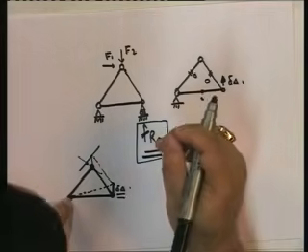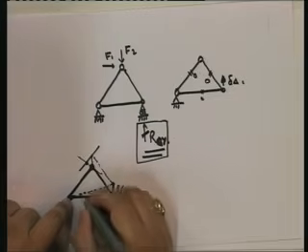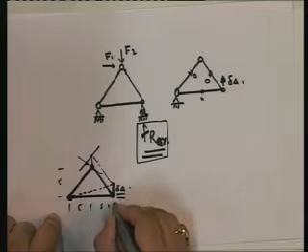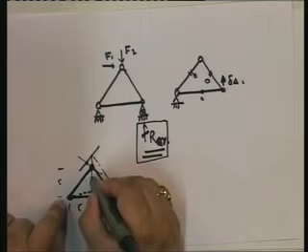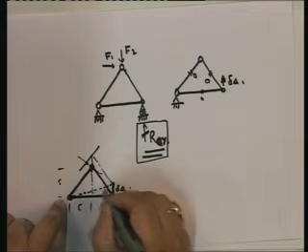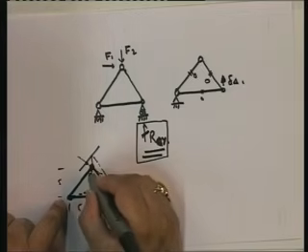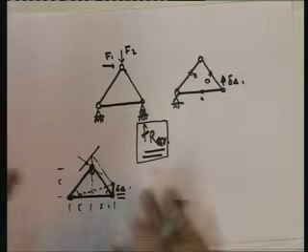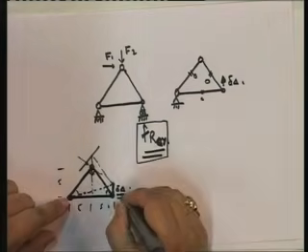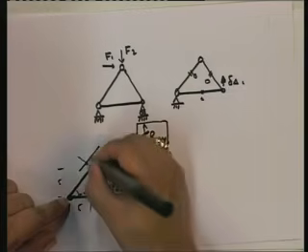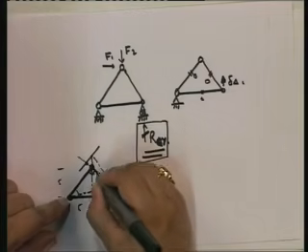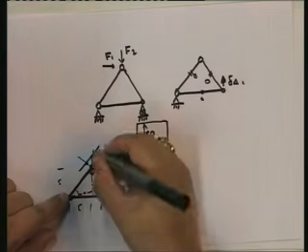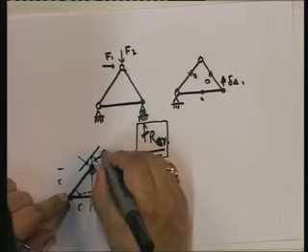Where is that point? Let's look at it. The way I have drawn it, with this as 5, this as 5, and this as 5, this is actually 45 degrees, 45 degrees, and so this is a 90 degree. This is 45, 45. That's how I've managed the whole thing. Now if this is delta, when this has to move perpendicular to it, what does that mean? Perpendicular to this is this. So it moves parallel to this member. So this part is delta.